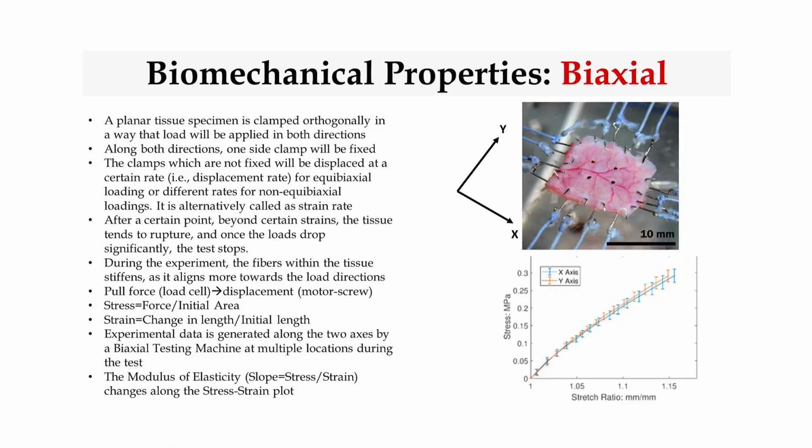So I'm going to explain about stretch ratio later in the classes, right? But let us just assume it's strain plus 1. The entire plot is being shifted by the number 1, right? Stretch again is unitless, similar to strain. You're looking at the stress on the y-axis. Here you're looking at two plots.